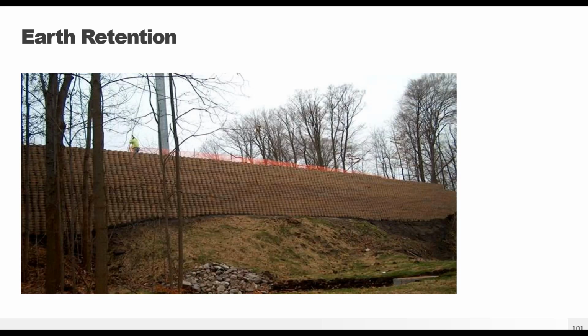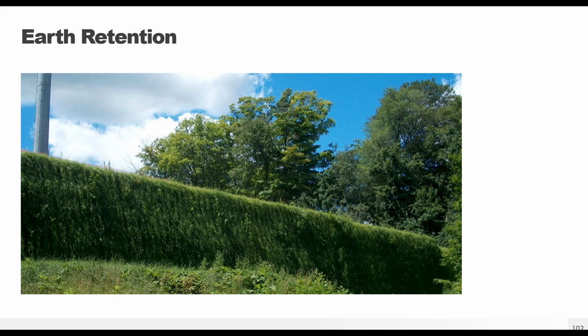Now, this is a project, this is a reinforced wall. This was to prevent a slope from a global failure and stabilize the line. So I like to show this picture because this is what it looked like in late fall when we put the wall up. And that's what it looked like by mid to late summer. You can see a complete full establishment of that vegetation in the wall. And most of the time you don't even see our GeoWeb walls. They just blend in. But once again, we can fill that front fascia if you're looking at a high stress area, it might get some flows.